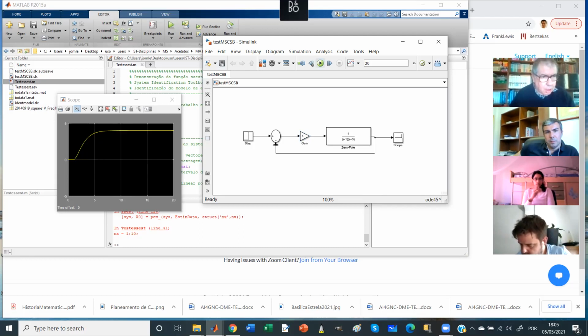Okay, so you have this type of response that does not oscillate. It does not go to 0. Now the 0 has been shifted by the fact that you have the reference. Now, what happens when we increase more the gain? What was our theory? It will go to the reference, but there will be oscillation. So let's place, say, 6.